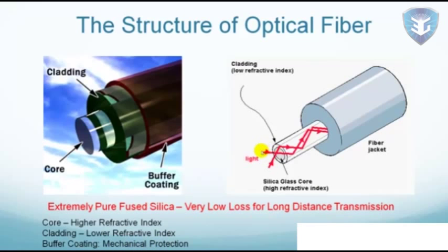The right picture shows how light is coupled into the fiber's core and bounced back and forth in the core and travels along the fiber. The core and cladding layers are all based on fused silica, which is a type of glass. But this fused silica is extremely clear, with almost no impurities. This transparency is extremely important, so that the light can travel for a very long distance, such as hundreds of kilometers with minimum loss. This makes trans-Pacific and transcontinental fiber optic communications possible.